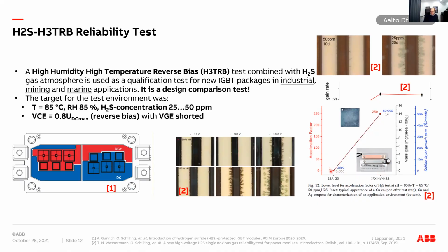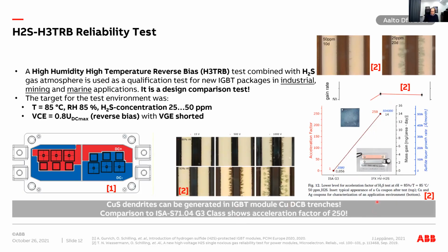It's actually 2000 angstroms per month, and now they had in this test 504,000. So it's 250 times more than here. So the acceleration factor is 250, which actually stands for, I think, 20 years after a 20 days test. So that's already something. With these coupons, you can estimate a little bit what the acceleration factor is, and it's highly standardized. So in that sense, it's good.